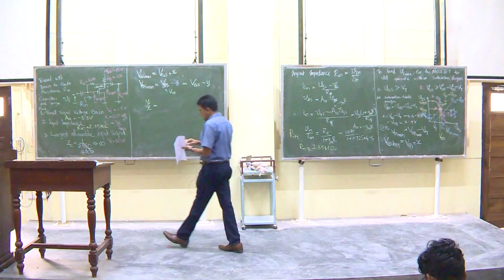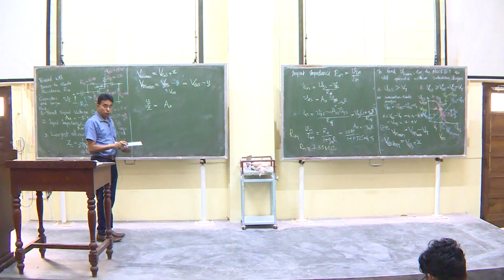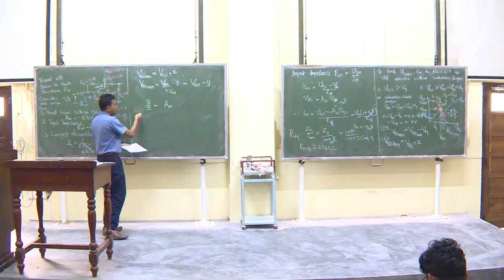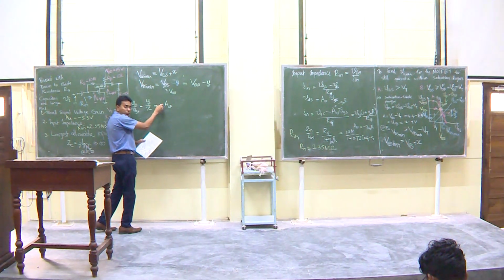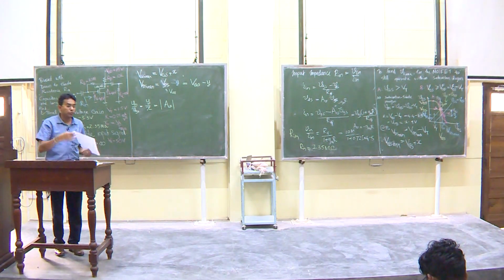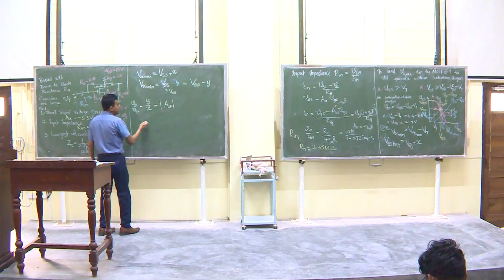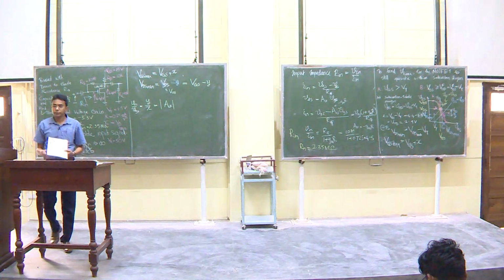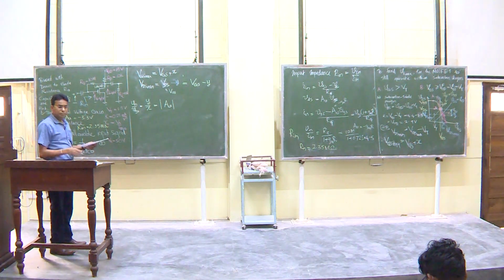So, therefore, this is equal to AV, voltage gain. Voltage gain is what? This is VDS divided by VGS. Obviously, this is a negative value, but what I am interested about is the x divided by y, not the direction of it, right. We know that AV value is equal to GM times R, something that we calculated earlier.